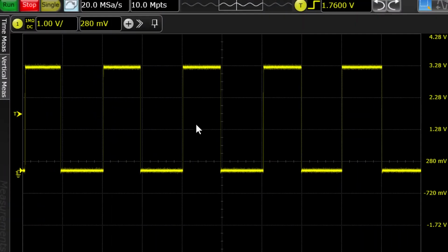And then lastly, I wanted to show you the output of an anemometer. This is the one that I'm going to use for the demo that we're going to look at next. Basically, I connected an oscilloscope to the output pin that's being pulled up to 3.3 volts to measure the pulse. And of course, I spun it with my hand to create these pulses. So the idea is if the wind was not blowing, we would just see a DC level pulled up to about 3.3 volts because of the internal pull-up resistor of the ESP32. So I spun this and we can see these pulses.